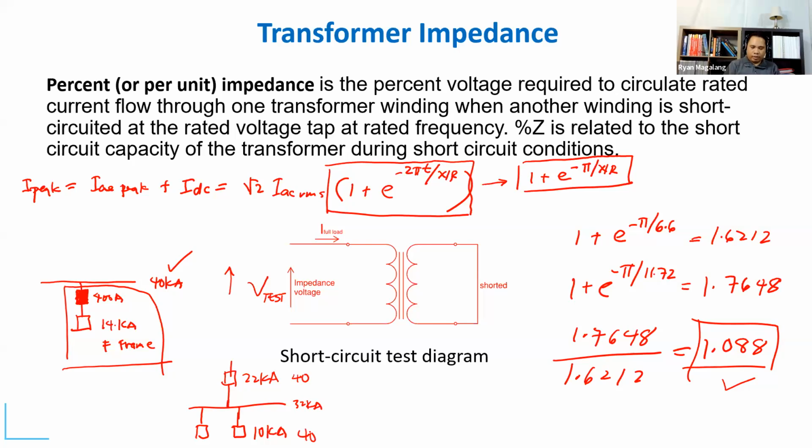But this series rated panel is UL tested, so that's why it allows you to install the lower rated branch circuit, because they have to be coordinated again, just like this fuse and breaker scenario here.